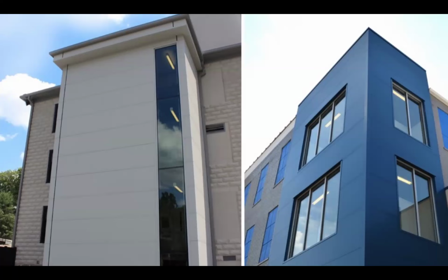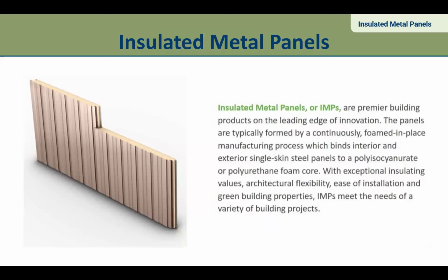That is done intentionally because your R value is based off the minimum of the panel thickness, not the average, not the thickest, but the minimum. So if you put in a lot of ribbing, you're buying and paying for a lot of insulation that you're not getting the benefit of. So to that end, insulated metal panels typically have very minimal striations and fluting in them to make sure we're getting the most efficient product possible.